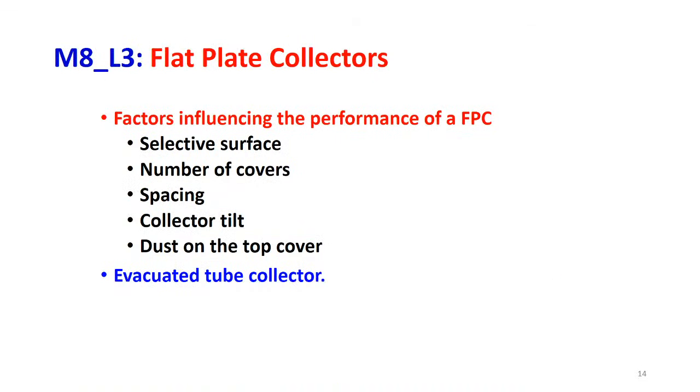And in module 8 and lecture 3, we have discussed different factors influencing the performance of a flat plate collector. So what are those factors? Selective surfaces, number of covers, spacing, collector tilt, then dust on the cover, and also we have introduced the concept of evacuated tube collector.